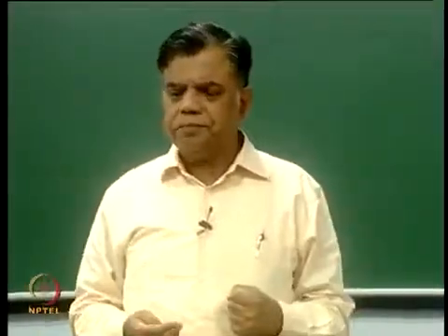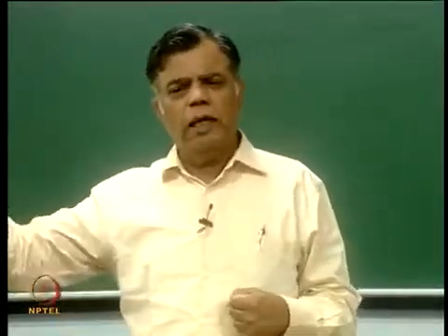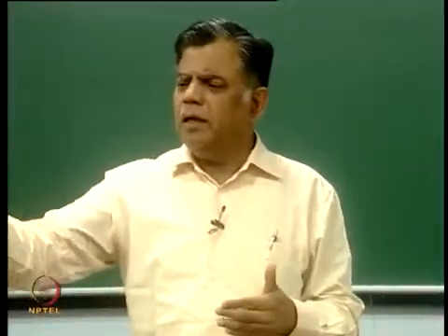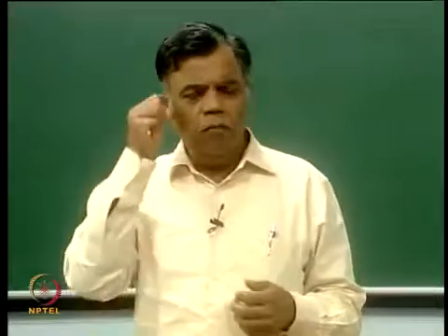Inertia by viscous forces. So as you increase inertia, it is your u ∂u/∂x actually. You please make it out. Reynolds number is inertia by viscous, so ρu ∂u/∂x divided by μ ∂²u/∂x². If you do that, you will just get ρVd/μ, that is Vd/ν, V being a characteristic velocity.